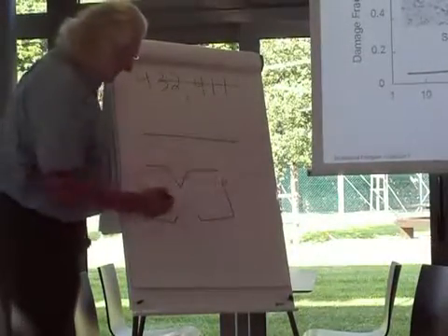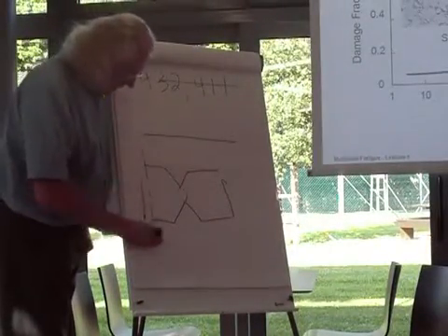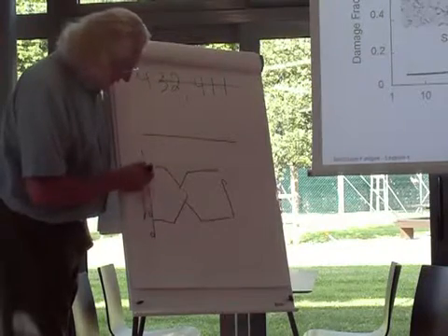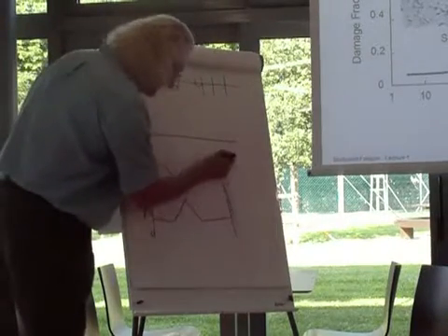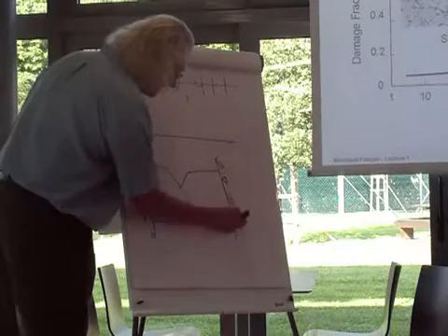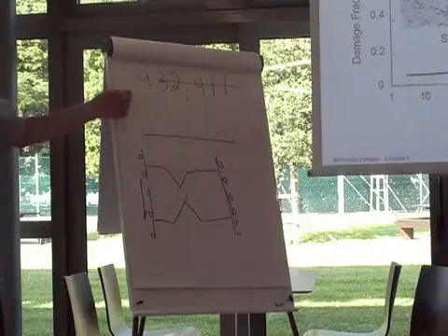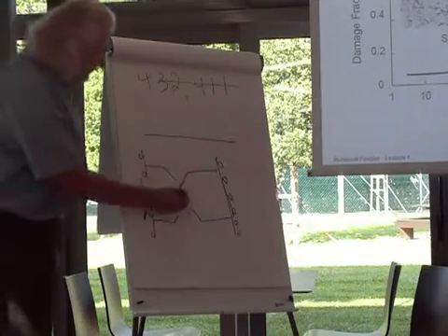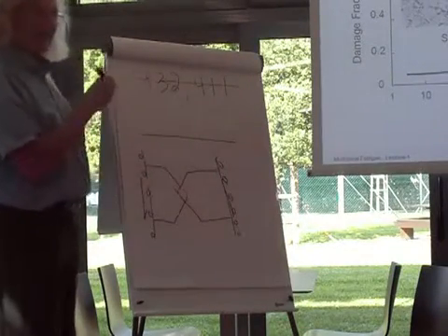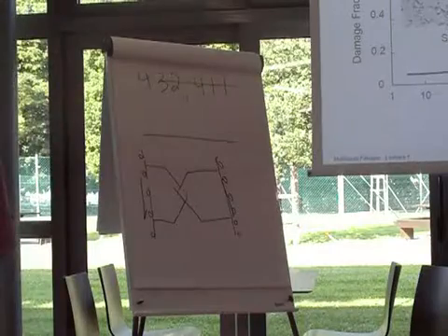Because in order for this to be the boundary condition, this has to have no bending at all. So this has to be fixed from any kind of bending loads. And it's impossible to do that experimentally. When you actually do these kinds of things and try to grow cracks, you get this, and then the things come off like that.